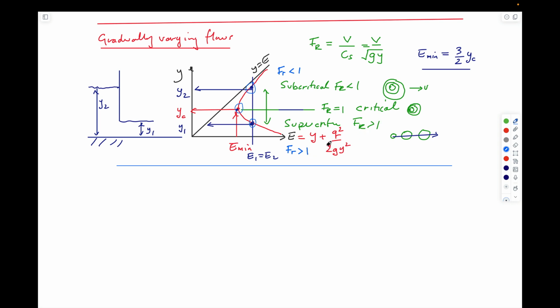And in the physical sense, what it means is that if it's flowing at the critical velocity, the flow velocity is actually equal to the wave speed, the celerity wave speed. So if this term is 1, and you put a drop of water in and look at the ripples, they'll all radiate concentrically from that system. If it's subcritical flow, if you put a drop in, then always the center of that droplet will be contained within the circles, except they won't be concentric circles because the flow is dragging it downstream.